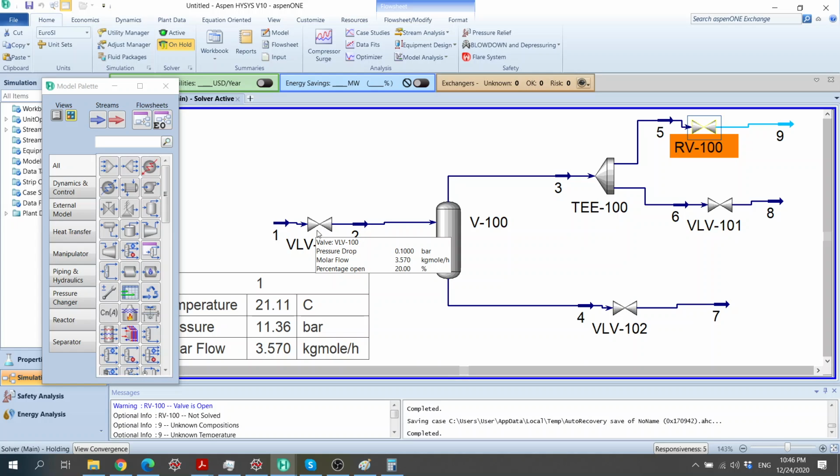I just put 20%, and after some time we just leave it open 100%, and then the whole gas will be popping up here, entering these vessels, and hopefully the pressure will increase, obviously, and then it will open this valve. But for that we need to make sure that we have pressure control first for this guy, or maybe not necessary, depending on how the simulation looks.